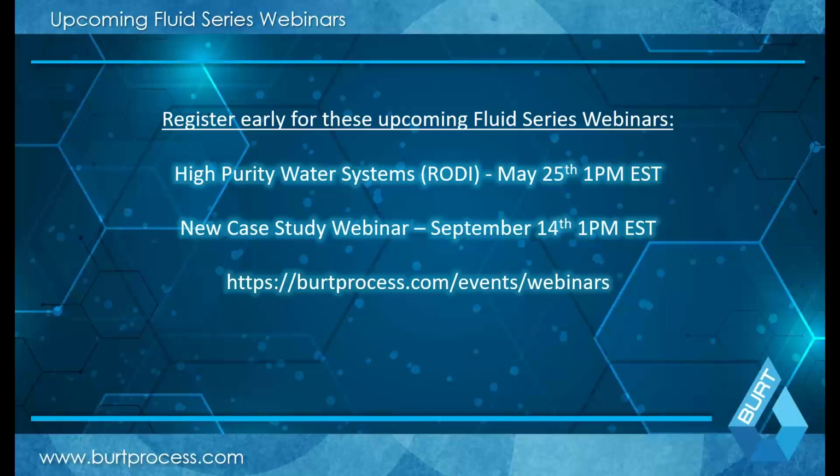The reason I like sulfuric over HCl is really the lack of venting requirements. Sulfuric acid has a very low vapor pressure, so you don't have a lot of venting in those cases. When you have HCl in your system, a couple of things come into play. It's a very strong acid, and people do use it for certain applications. What you really need to do is vent your reagent tanks. Usually you need to pull some kind of negative vent on them. You may need to coat your agitator in your tank, and you definitely need to pull a vent or negative pressure, instead of an atmospheric pressure vent, off of your pH neutralization systems.